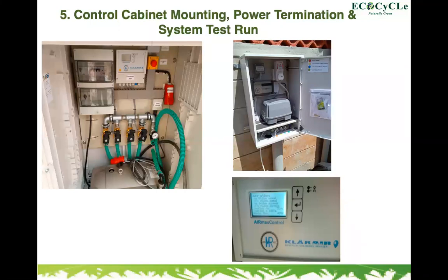Now, the PLC is able to go to something called an eco mode, whereby it can accommodate the amount of sewage that is being produced at that time. It's able to determine, for example, if the system is supposed to treat 1.5 cubic meters of water per day, and now we are producing the sewage, the system will detect automatically and treat the appropriate amount of sewage.